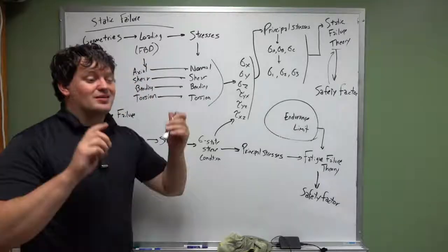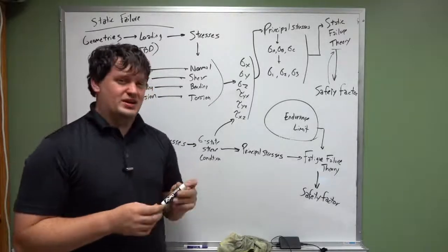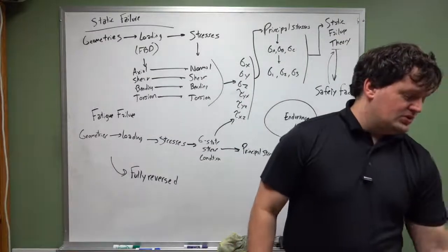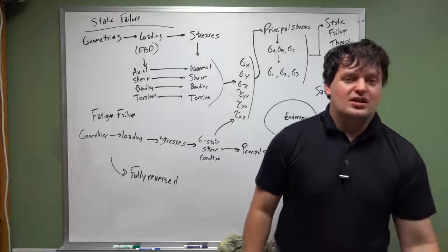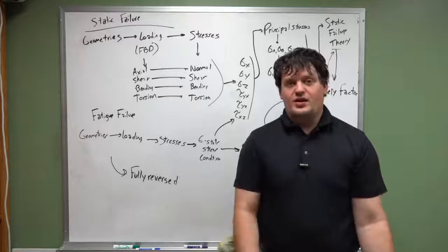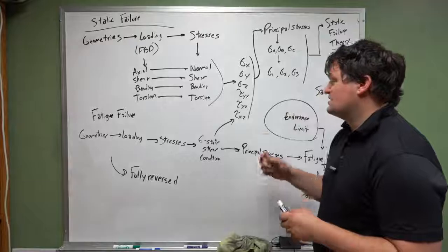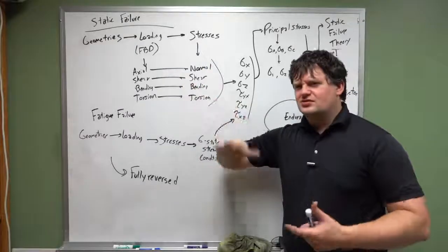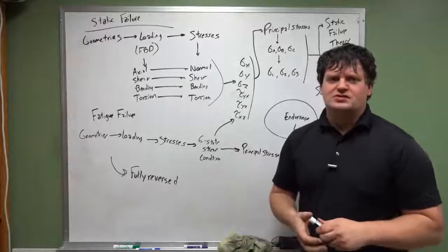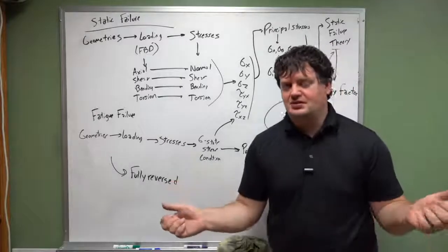What we're going to be talking about in our next video, which I may either post this week or next week, just to finish out fatigue loading, is how you handle it when it's not fully reversed. It's just a different way of calculating it. And it does have some effects on the endurance limit. The endurance limit is actually smaller for non-fully reversed loading. Like I said, this is the worst condition of loading you can possibly apply to something.